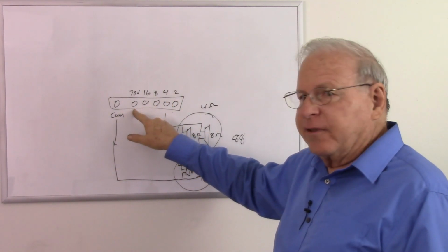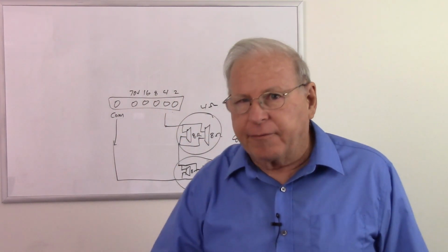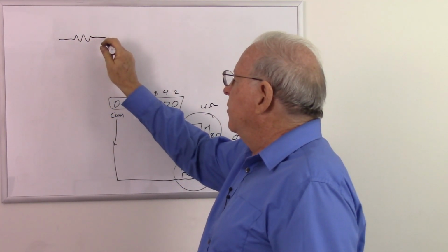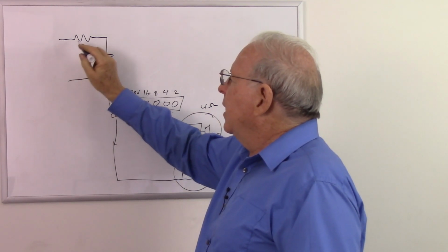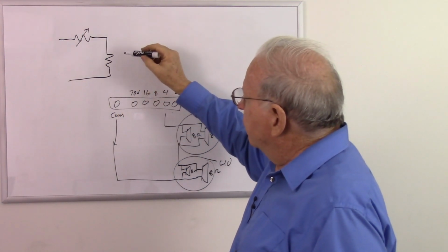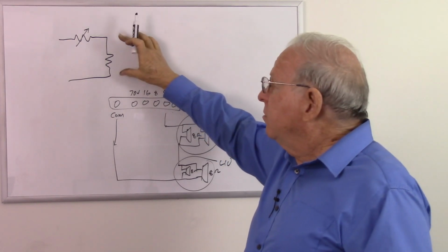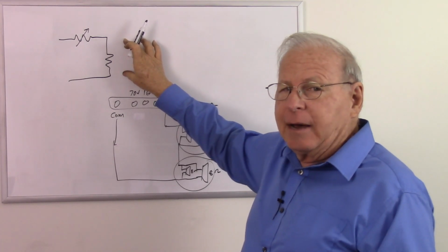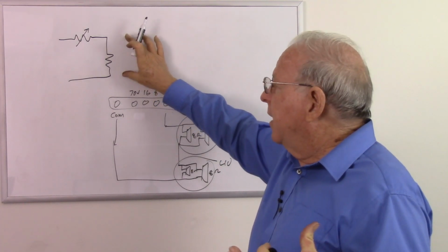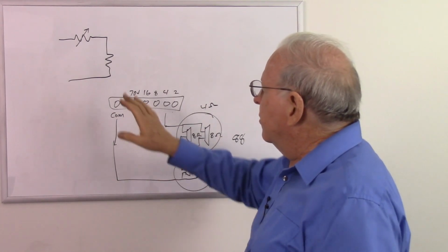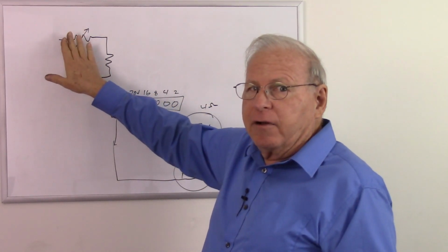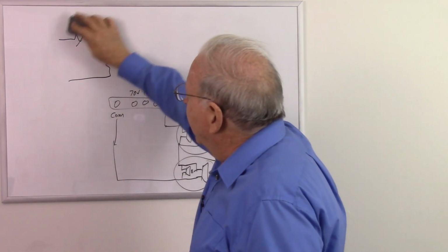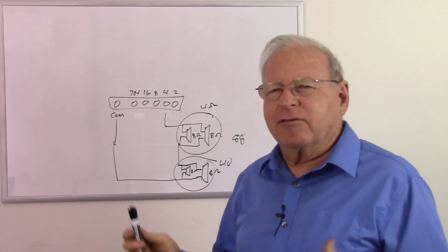We have a system where the amplifier now acts more like a regulated power supply. Remember, the regulated power supply, if I just draw the model of that, there's the output impedance of the power supply, there's the load impedance. And remember, this acts like a variable resistor, so that as this load impedance goes down, the voltage across it is going to go down. And so this impedance is going to go down to match to bring that voltage back up. Watch my videos and read the material on power supplies to fully understand that. But basically, the impedance of the amplifier now is going to change to keep this voltage constant. Well, this is not a constant voltage situation because we're going to have loud sounds and quiet sounds.